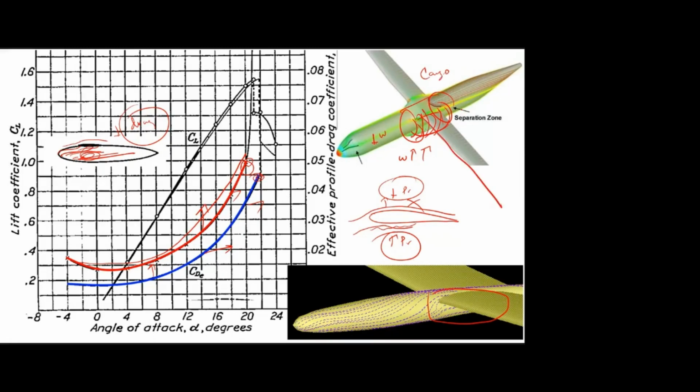Then to withstand that, we have to produce more lift. So the wing span, wing area, everything will be very high. Also, it has to withstand a heavier engine. Okay, so we need better clearance from ground to the engines, all those things. So for the cargo type heavier aircraft, we are going for the high wing. Almost all other commercial aircraft, we are going for the low wing only.